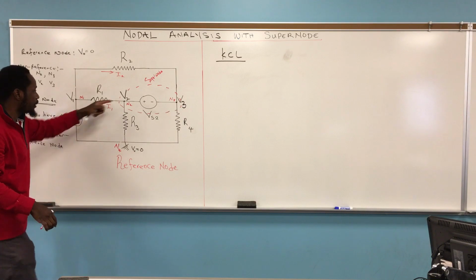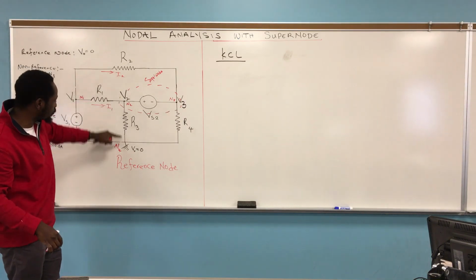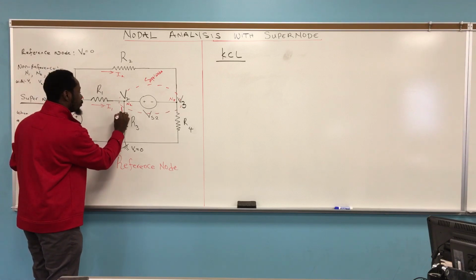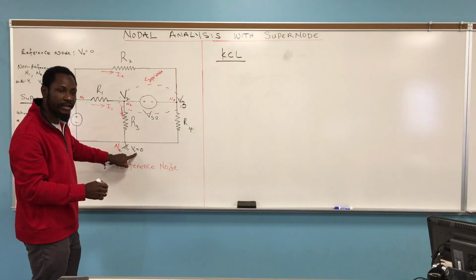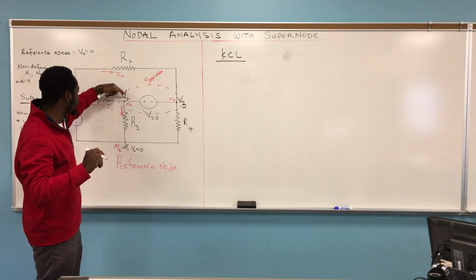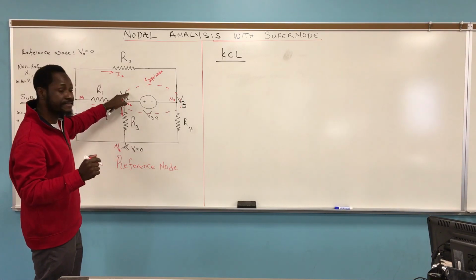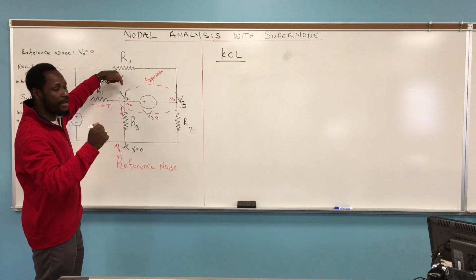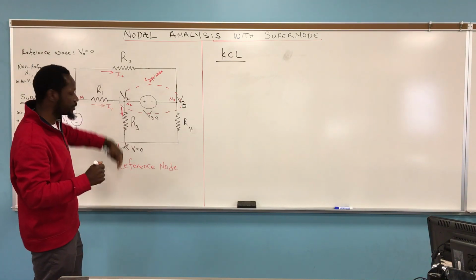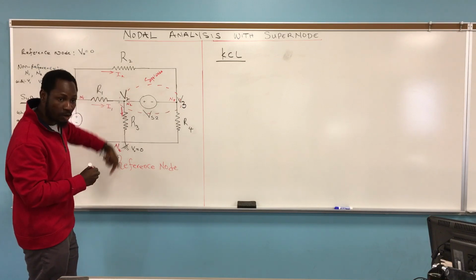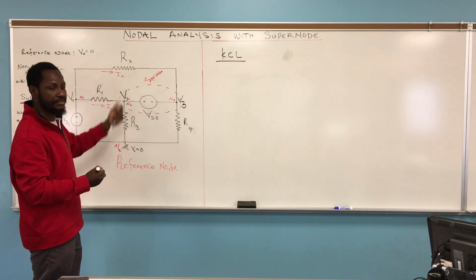Likewise this. Now for this one between V2 and ground, I like to point them downward. Why? Because I have my ground here. I am assuming that the potential here is higher than the potential here. Well, this is 0 unless this is negative. This is going to make the current go the opposite, outward, right? Not towards it.